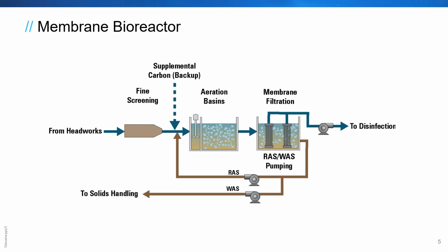I'm not going to belabor this. I'm sure all of you have seen a million presentations over the last 20 years about what an MBR is. But the basics here is, instead of a conventional plant where you have clarifiers and filters, you put in a barrier membrane separation process, which becomes the best clarifier in the world, so to speak. And then you can run your aeration basin at a higher mixed liquor and get a higher quality effluent, in less space, kind of following along with the intensification concepts that are being talked about more and more these days as we have challenges with existing footprints, and then making plants that are already in existing footprints do more relative to nutrients or even potable reuse.